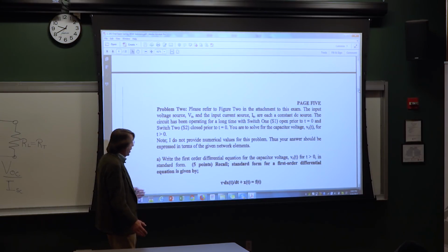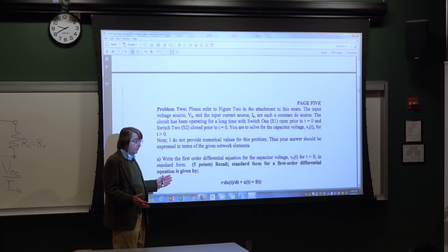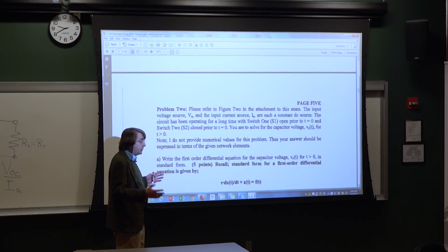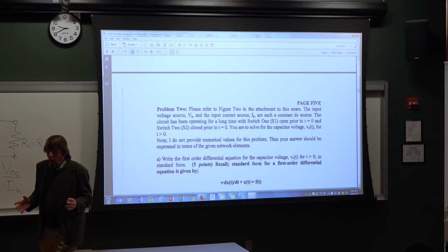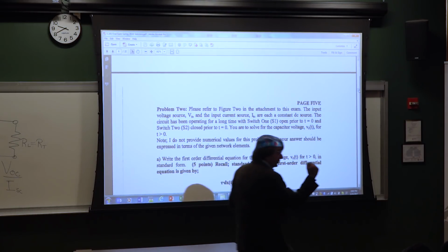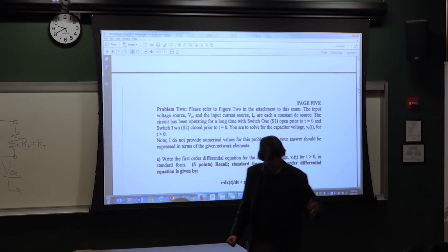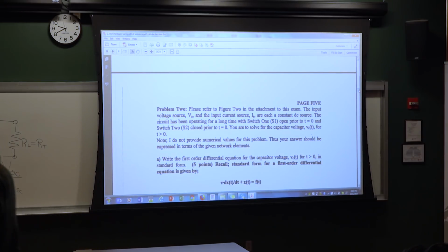Step A, write the first order differential equation for the capacitor voltage for t greater than 0. Are you going to use nodal or mesh if I'm asking you for voltage? What's your first instinct? Nodal. Very good. The force is strong with you, young Jedi Knight. So we go with nodal.